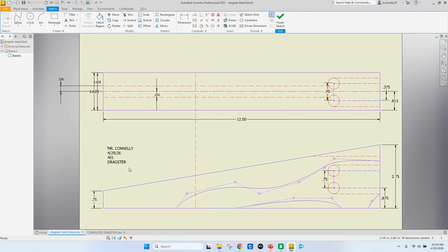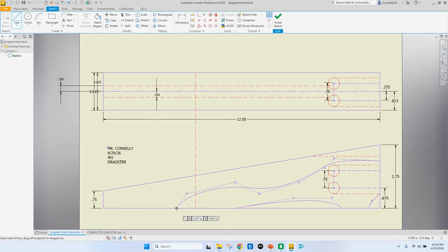Next thing I'm going to do is put in some construction lines to help me line up my view for when I do my top view. So I'm going to go back to lines here. Any guidelines we're going to make yellow. So I'm going to get my green dot. I'm going to bring it all the way across here. Make sure I set it to 90 degrees and click. I'm going to go to this. This one I'm just going to go to this line, and I'll do the same thing for these 2 points here. Like so. We're going to hit escape.